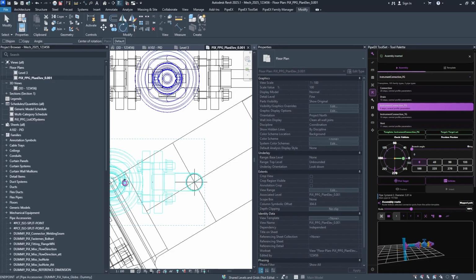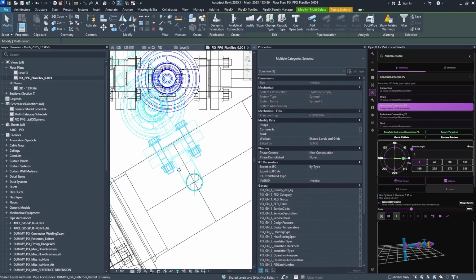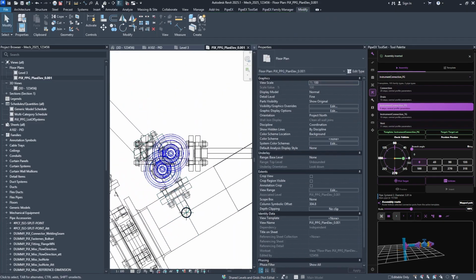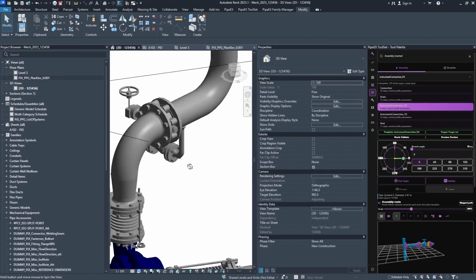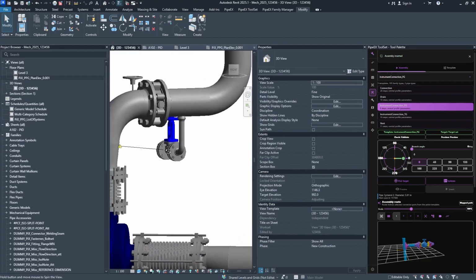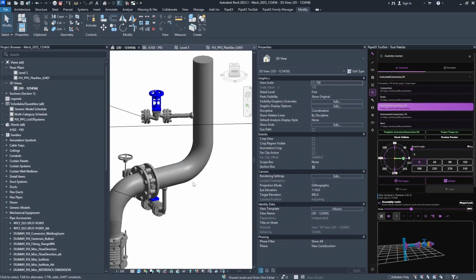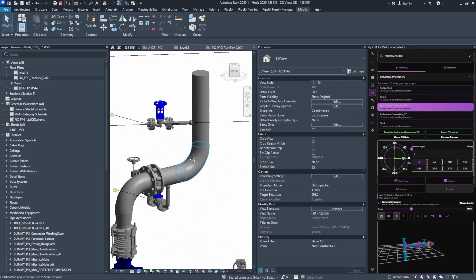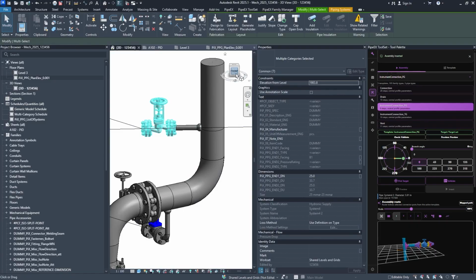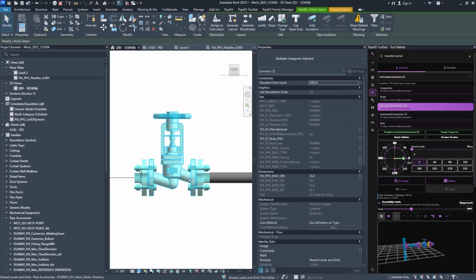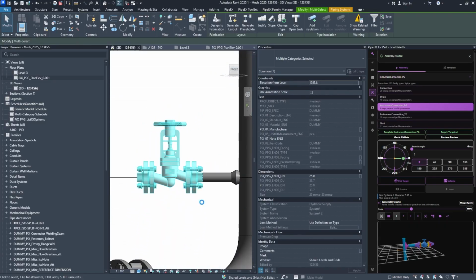Click on the handle on your screen, move the center of rotation, and just rotate it. And this is how you can rotate any kind of component in Autodesk Revit. This part I also think is a little bit too long, so by using arrows I can shorten it.